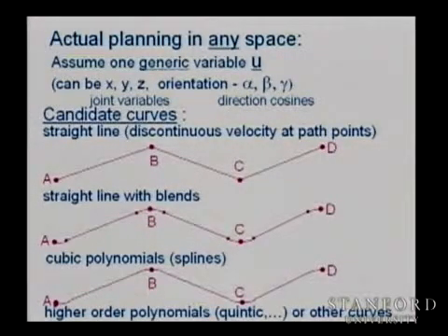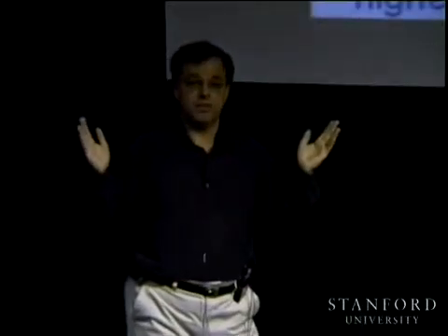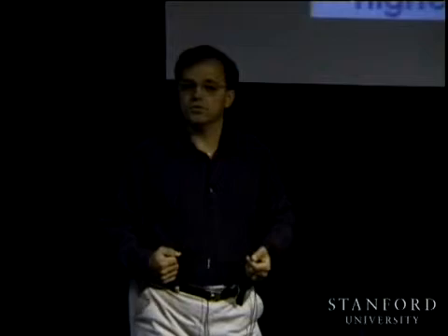Say you're starting from a certain position, ending at a certain position, starting with velocity 0, and ending with some velocity, and that's about it. If you want to control acceleration and deceleration, you need a higher degree polynomial because you need more coefficients to satisfy that motion. We'll see that more in detail.